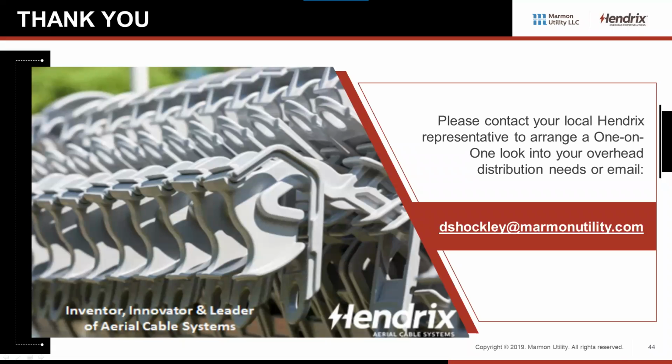There have been studies done at different voltages and different types of trees, because some species have more moisture to them and all that other stuff. But it really depends. I think our official line on the useful life of covered conductor spacer cable is 30 years. But obviously that can be shortened by a lot of tree contact or a lot of incidents of tree limbs falling on it. So 30 years is right around the number when we tell clients maybe they want to think about swapping it out or replacing it.